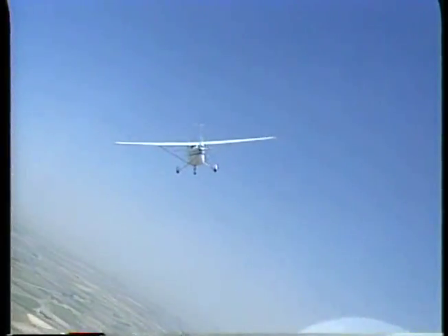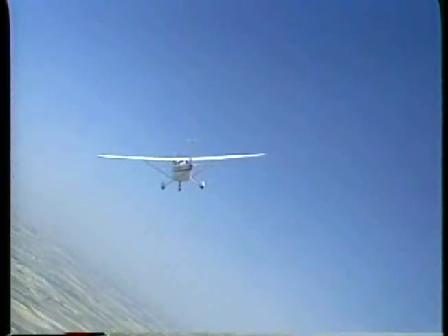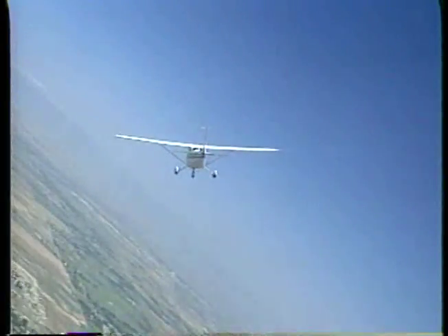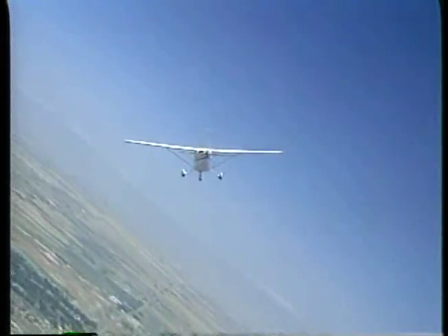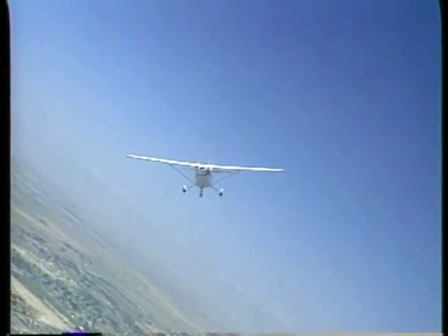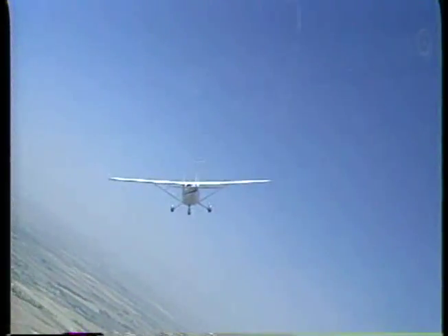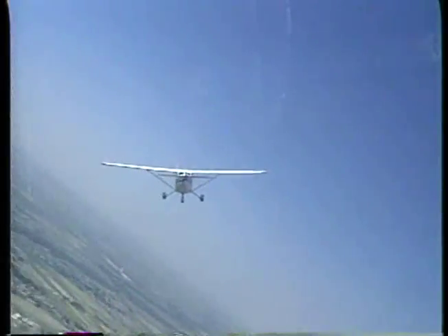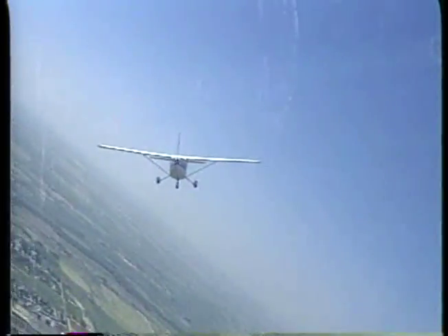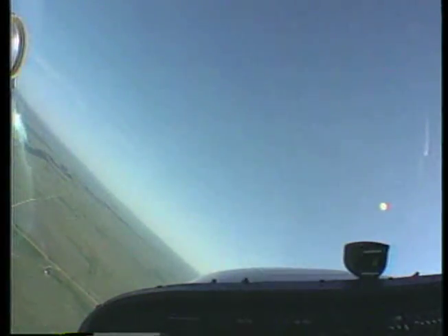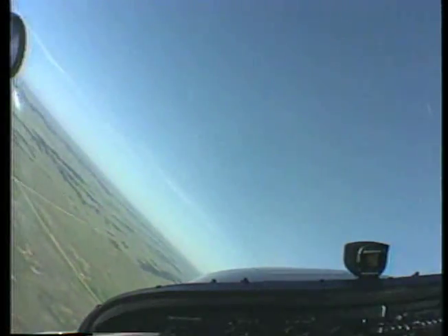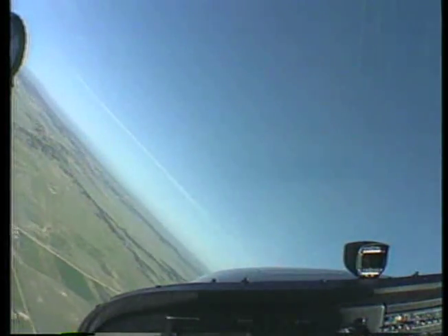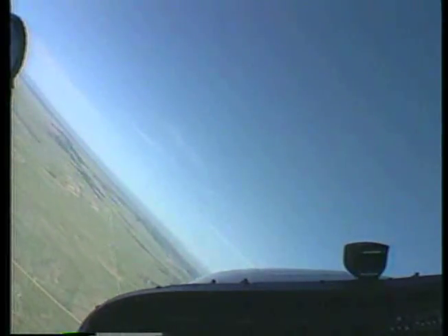After gaining proficiency in stalls, you will be introduced to more advanced maneuvers, such as constant altitude steep turns. This maneuver consists of a constant altitude 360-degree turn with a bank angle of 40 to 50 degrees. The practical test standard, PTS, requires that you be able to turn in both directions. Steep turns help you develop coordination of pitch and bank while maintaining altitude at a constant power setting. They also develop smoothness, orientation, and division of attention.